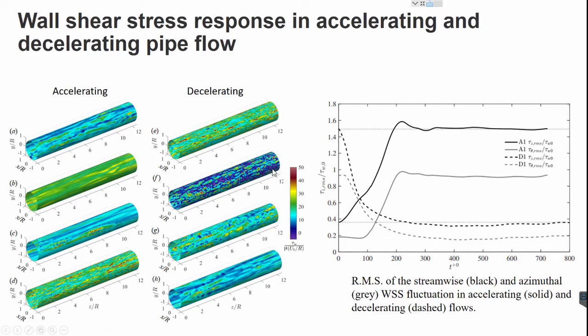So we have negative wall shear stress in large regions of the flow, which means that we have a lot of flow separation. And this flow separation is related to adverse pressure gradients and inflectional velocity profiles. I'm not going deep into that, but it makes the flow unstable. After the flow deceleration, it seems that turbulence is being dampened, and finally we get our final steady state.